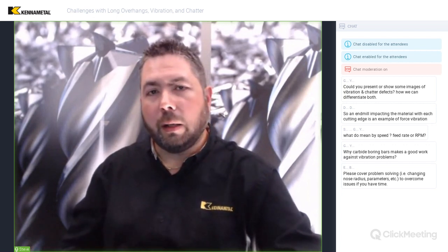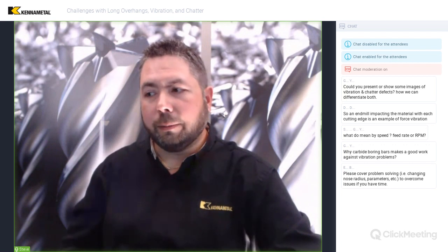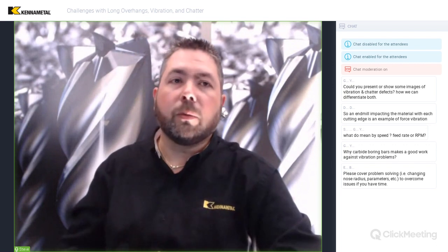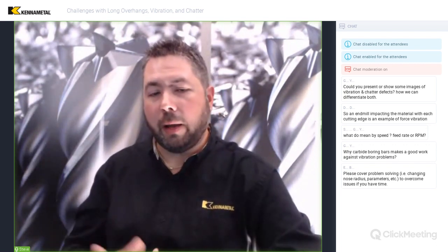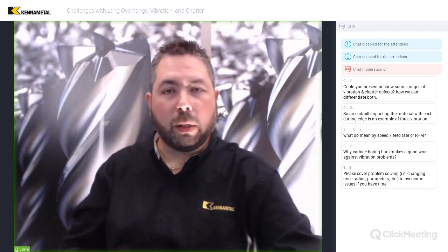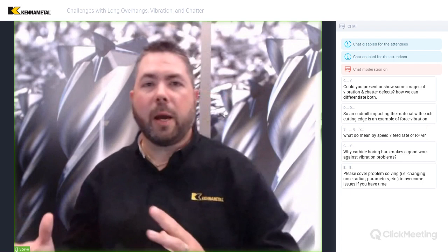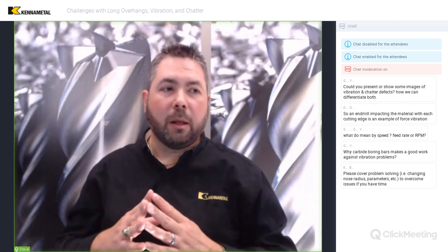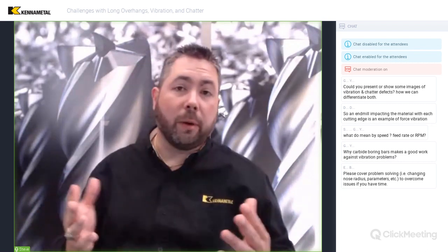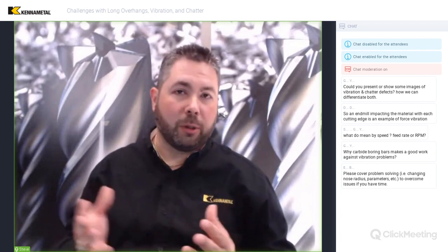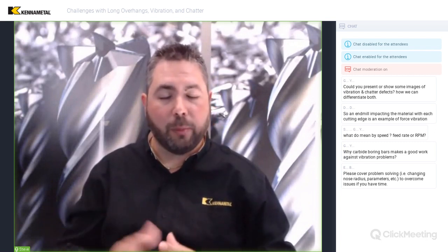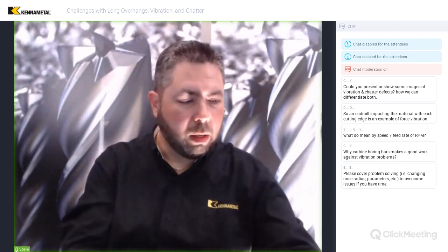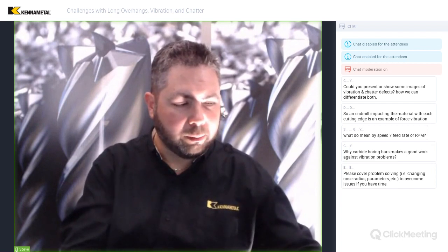Another thing that you can look at is whether or not you can use a more positive insert. So if you've checked everything else and you still have trouble with chatter, that would be another thing to look at. So again, what would that do? Just go back to our short overview of vibration theory. We need to worry about the force input, right? If we're able to reduce the force with a more positive cutting insert, then that will certainly help the situation. So those are a few things to think about.